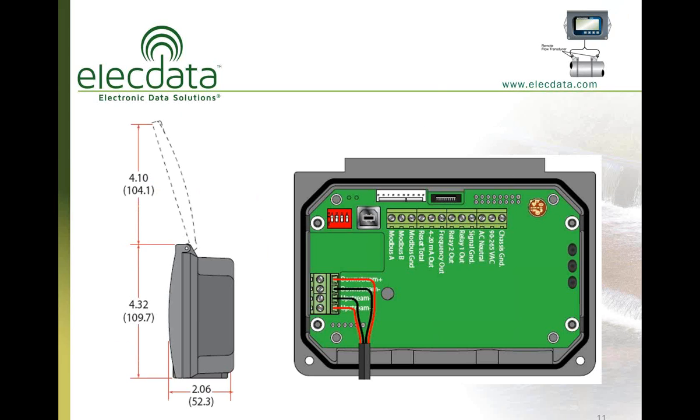This is what the inside of the UTM10 flow meter looks like. It has a hinged lid that you can raise up, and that exposes some terminal posts where you can wire your sensor. The sensors come detached from the meter with bare wire leads, so you can thread the sensor cable through conduit and then route it into the meter and attach it to the terminal post.